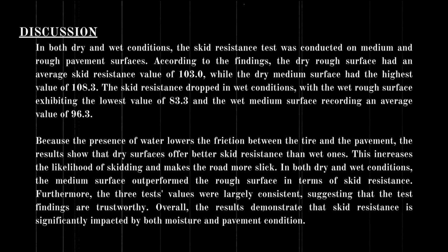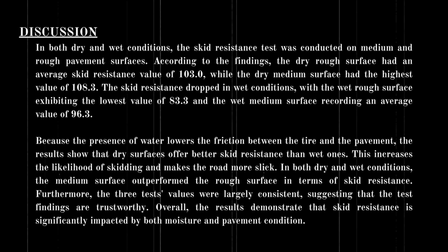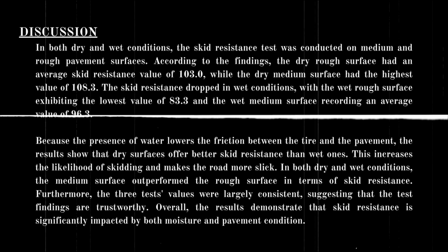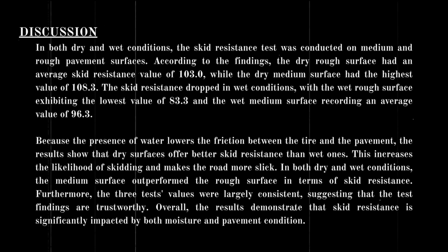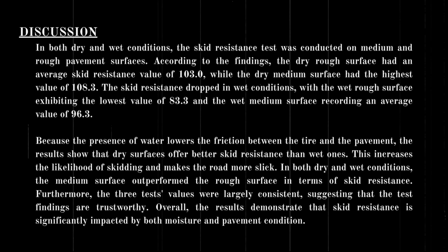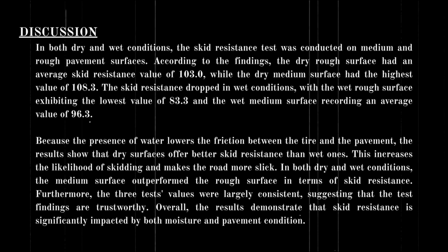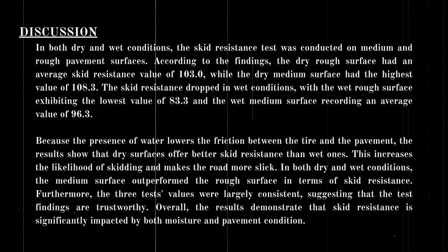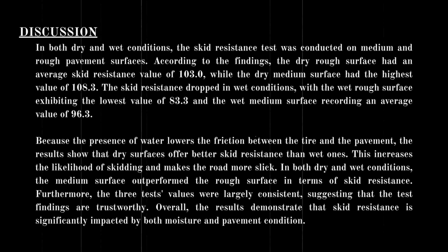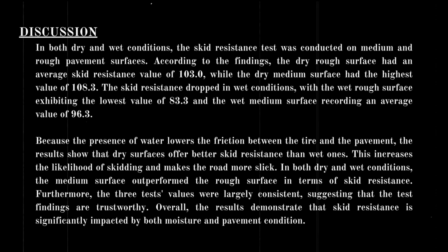Basically, skid resistance is what keeps cars from sliding and prevents accidents. Because the presence of water lowers the friction between the tire and the pavement, the results show that dry surfaces offer better skid resistance. The 3 tests conducted were largely consistent, suggesting that the results are trustworthy. The results demonstrate that skid resistance is significantly affected by both moisture and pavement condition.